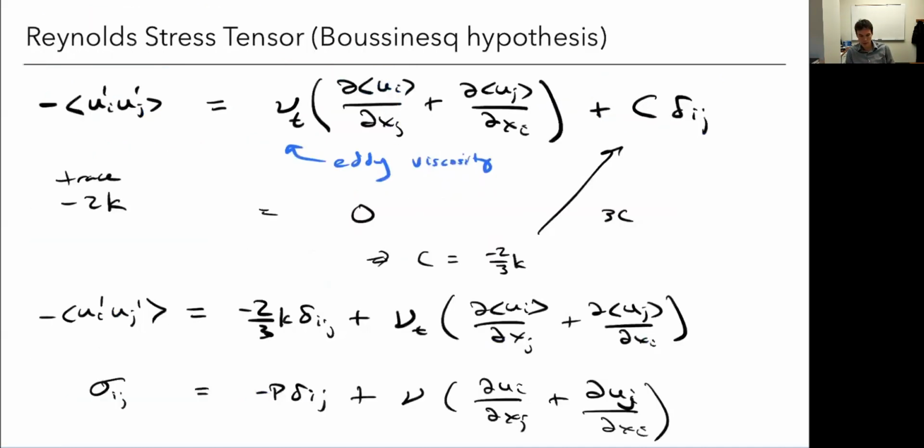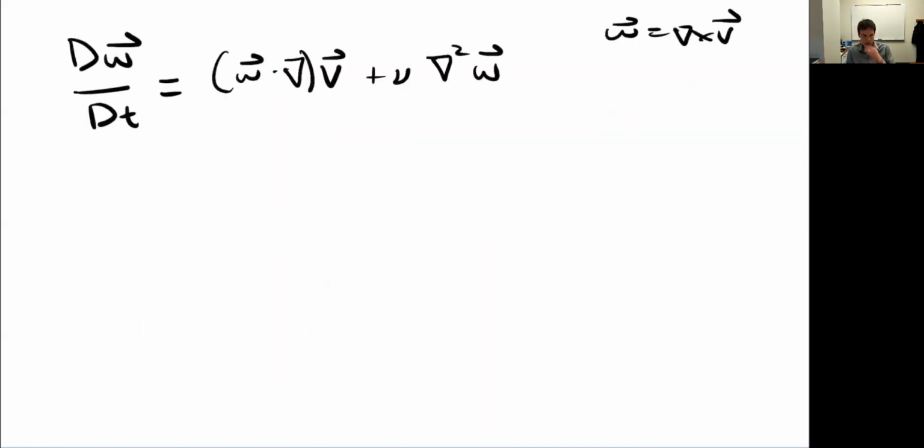And so this is actually kind of a philosophical thing in turbulence, that fundamentally it's 3-dimensional. It doesn't really make sense in 2D, because in 3 dimensions, you get that stretching into the other dimension, right? Across the vorticity, you get the vortex stretching. That's what causes that energy transfer. And so you don't really have turbulence without 3 dimensions. And yet we use RANS in 2 dimensions all the time.